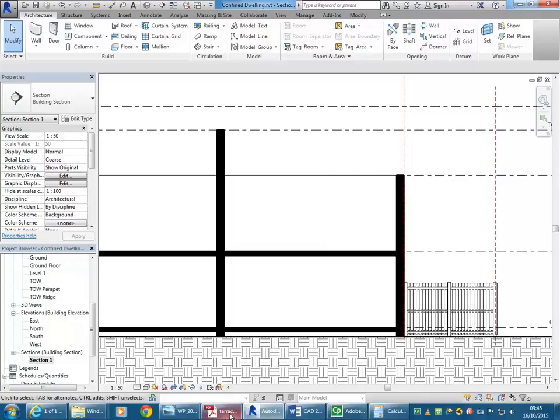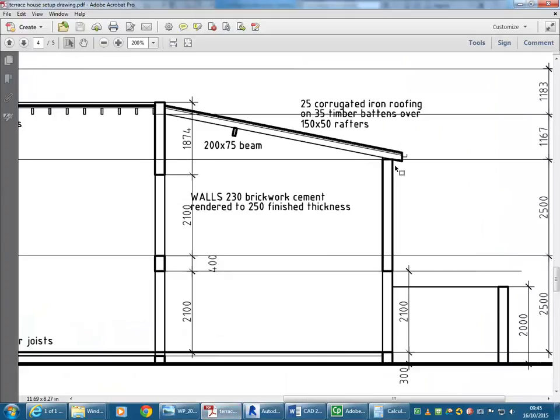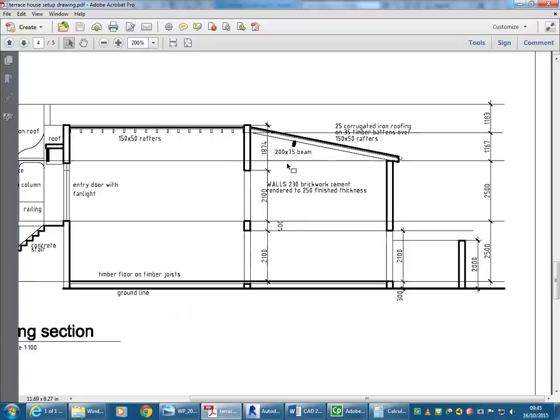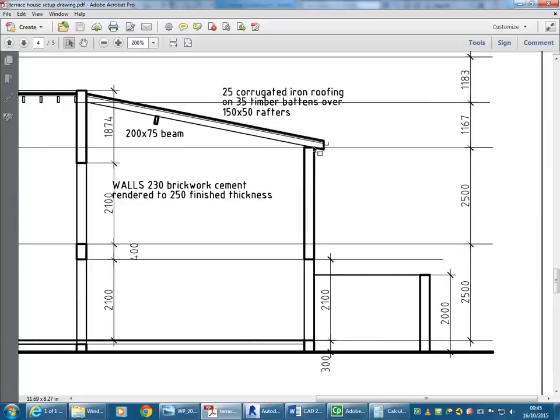And so, then looking back at the section, we've got no height there for the bottom of the roof on the higher point. But we do have a height for the bottom edge of the roof where it intersects with the wall, and that's really why you use levels for the top of the wall so often, because it's the pitching point for the roof, that intersection there, not the end at the top. Yeah, the point where the rafter sits on the wall. Yeah, exactly.